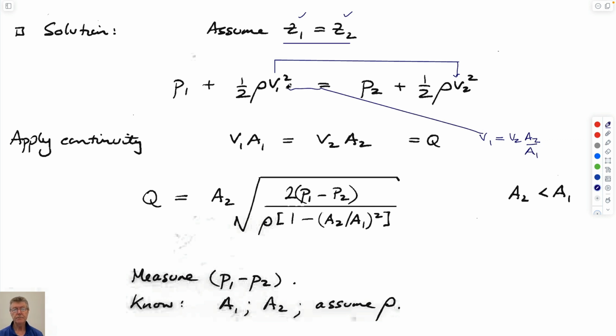We'd put that in here. We'd play around with this. I know we did that because we're getting the fact that volumetric flow rate is equal to A2 times V2, right? This whole expression, this is just an area times a velocity. That's a volumetric flow rate. Length over time, length squared, length cubed per time. So this whole term here is just a velocity. And this is how it works out if you just solve Bernoulli.